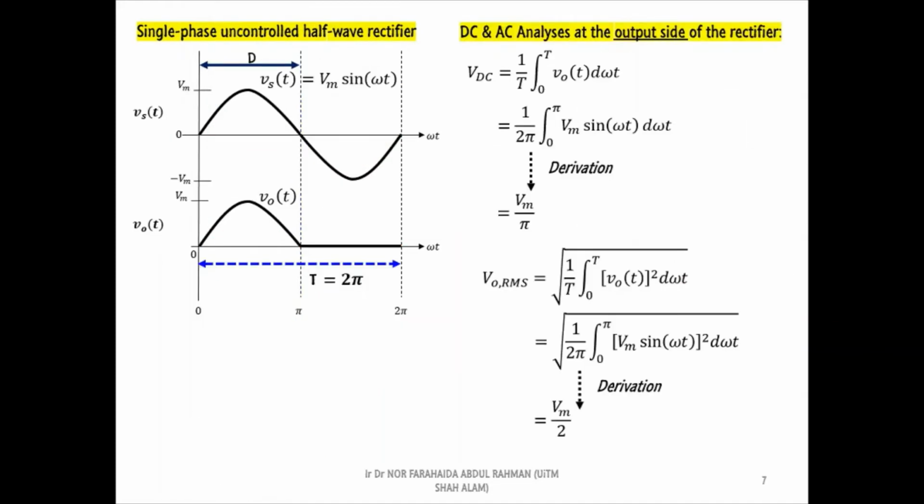For waveform analysis, we will focus on the average and RMS output voltages, ripple factor, and rectification ratio of the rectifiers. As usual, I will start with the waveforms and equations of a single-phase uncontrolled half-wave rectifier with resistive load. Now, I will change the waveforms based on the operation of a controlled rectifier. Based on the new output voltage waveform, the voltage equations will change as follows.